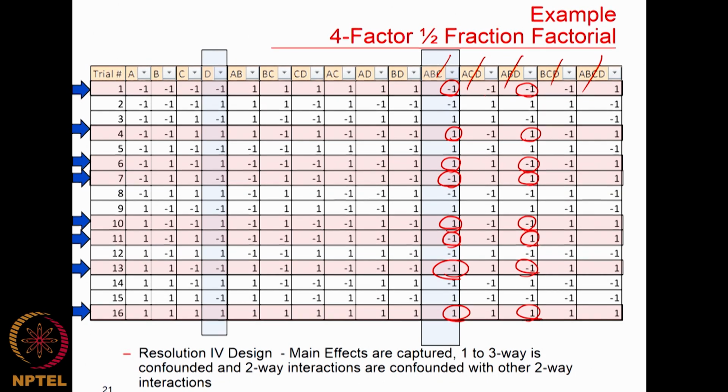Then you might also want to, A, B, C, D. Okay, this is a 4 factor experiment that we are doing. Then you will have to do confounding to bring this guy down back to L8, because if you just take only these 4, it will give you a larger 1, 2, 3, 4, 5, 6, 7, 8, 9, 10, but you need to bring it down to 7 because it is an L8 array. Then you will have to do confounding to bring those guys. So, the confounding will be between AB, CD, BC, AD, CD, the other one that is left.